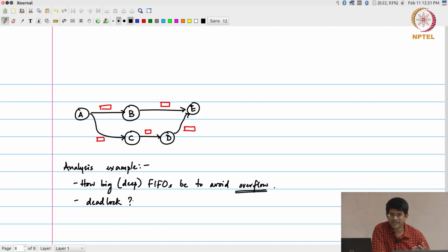One problem that you might have noticed already with these Kahn process networks is, how would you model conditional behavior? If I wanted to say, okay, if some condition is satisfied, do this. The KPN model by itself allows that, but the moment you bring in that kind of a conditional node, you can no longer say anything about FIFOs, because now it basically says a token may or may not arrive at a particular buffer.